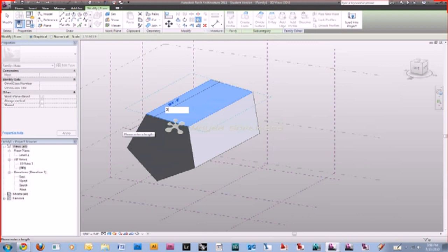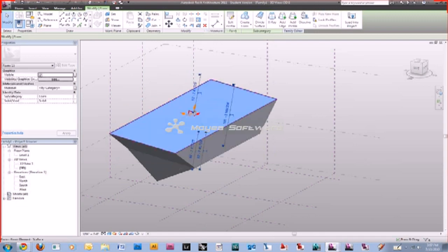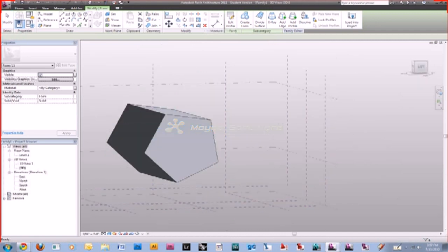Whenever you see a dimension showing up, you can go ahead and type in exactly what you want versus doing it graphically. So once I start to change this, I can type in now, 300 space 25. It'll just do a quarter if you did that. Space 11, it'll do like 14 inches, 300 feet and 14 inches. And then it'll scale it to that point. That's ugly though. Let me change it. It is ugly. So let's say I resize this.